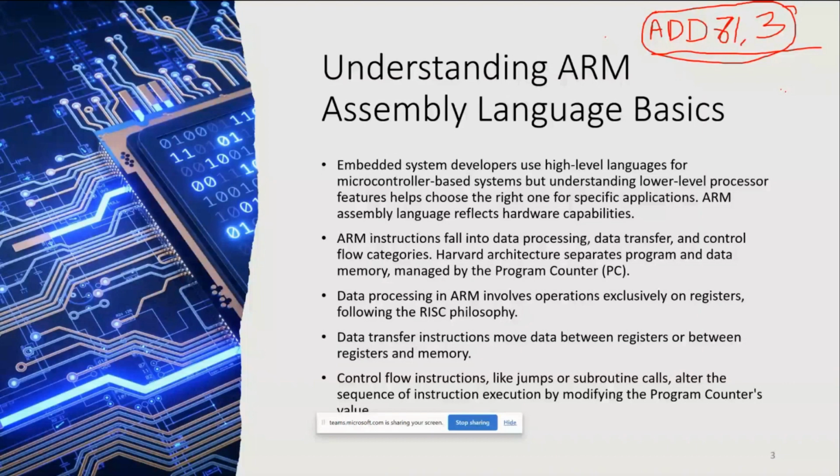So that is an instruction that you give the computer to do some work. While data, in the example, what is the data? Data and the marks. So there are two things, data and instruction. In the von Neumann architecture, there is a separate memory for data and separate memory for instruction. While in the Harvard architecture, and Harvard architecture is common in modern microcontrollers. So there is a separation between program and data memory. Instructions reside in program memory, while temporary data is stored in data memory.